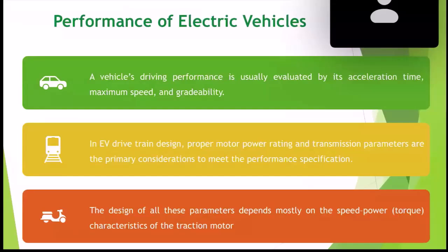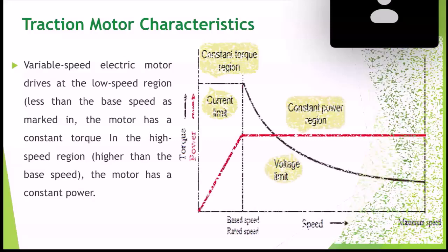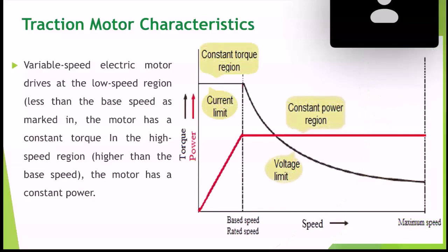And more importantly, while selecting the motor, the overall performance of the vehicle will be important. Overall vehicle performance means how much power needs to be produced, what the power band region is, what the torque band region is, and what the driving range and efficiency are. Likewise, the cost and these things need to be considered while selecting the proper rating of the motor. Typically, depending upon the traction motor characteristic curve, the motor will be selected while going through the motor selection process.